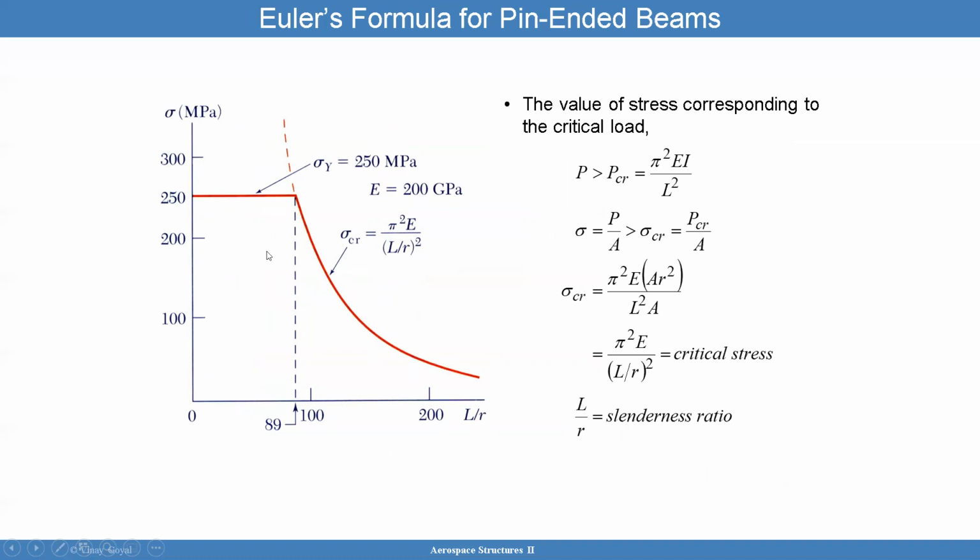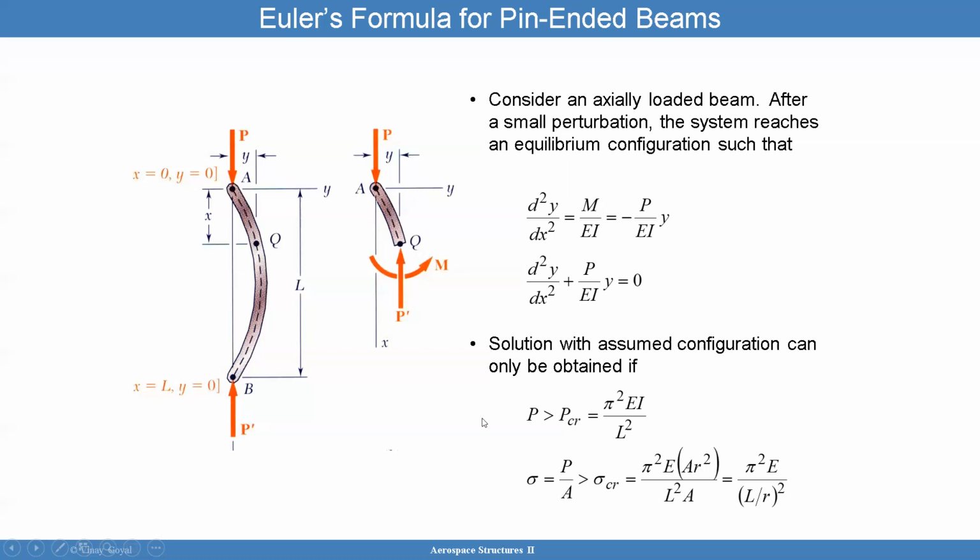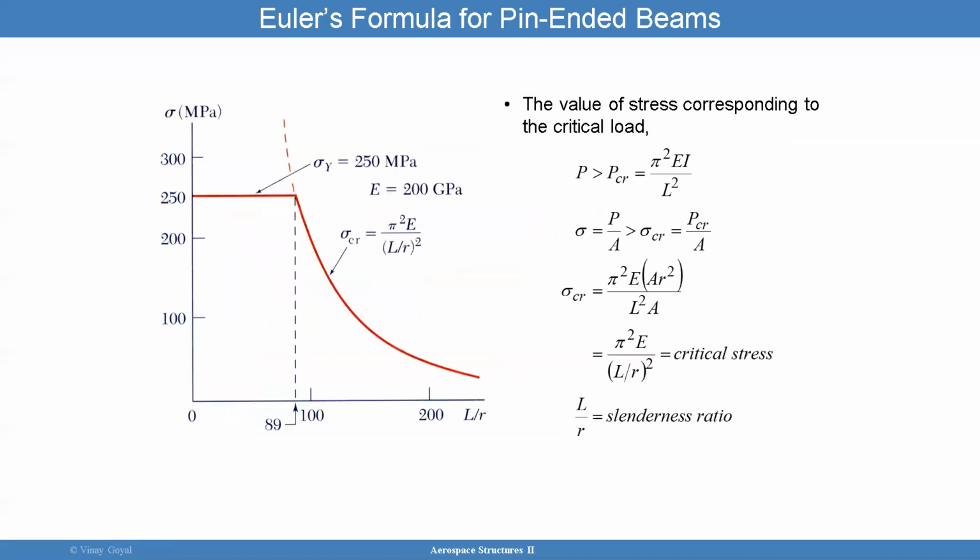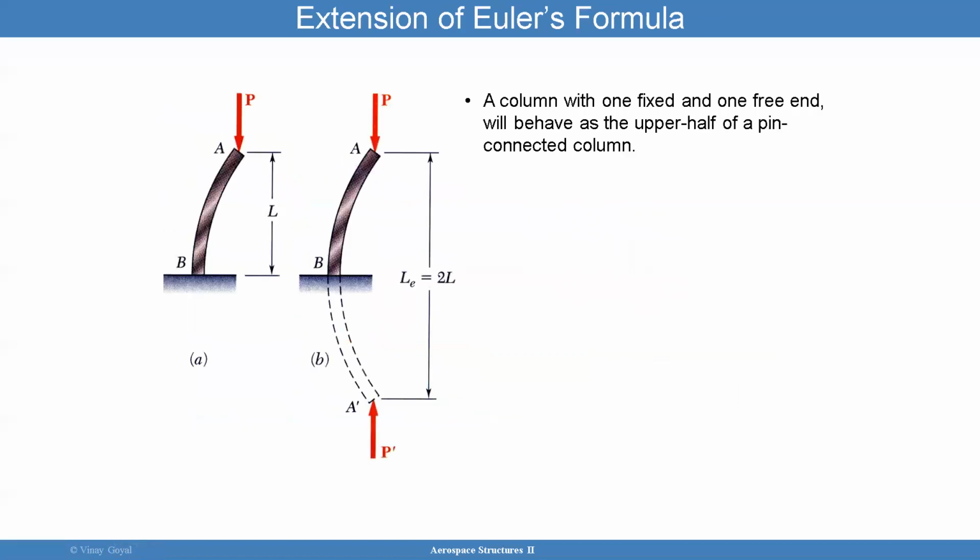So I'll just move on here, but the longer it is compared to the radius, say I have a circular cross section, for example, you will see the buckling now starts getting dominated in these regions of longer lengths. But when I look at a lower length, then stress can become the part that drives it. So it's important to evaluate both in real life.